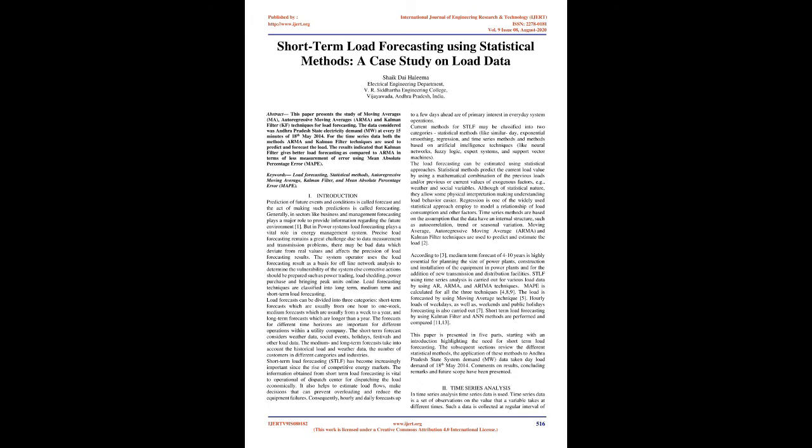The forecasts for different time horizons are important for different operations within a utility company. The short-term forecast considers weather data, social events, holidays, festivals, and other load data. The medium and long-term forecasts take into account the historical load and weather data, the number of customers in different categories and industries. Short-term load forecasting, STLF, has become increasingly important since the rise of competitive energy markets.